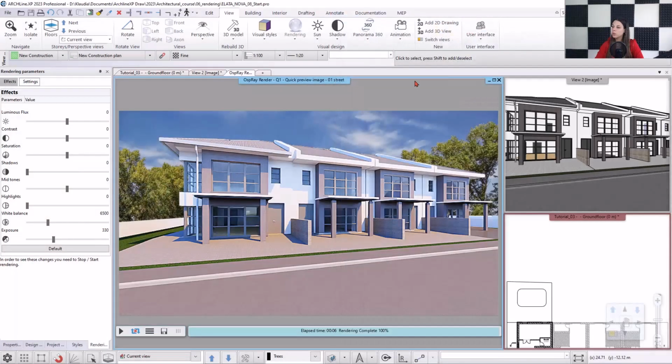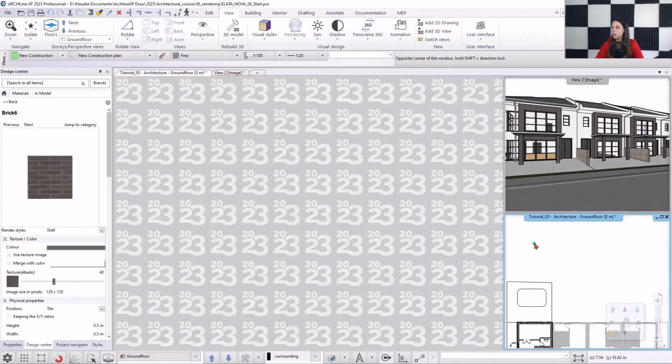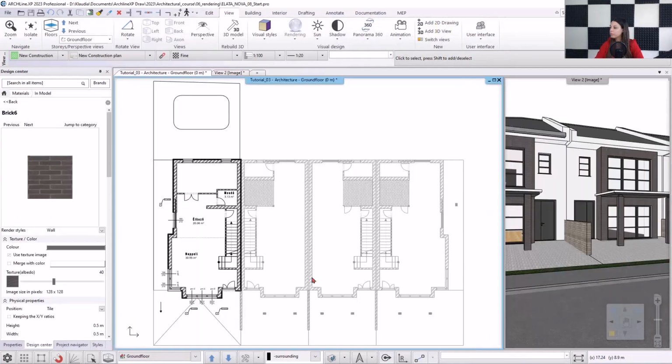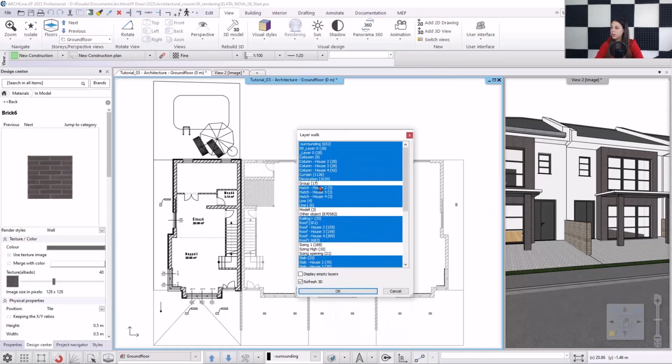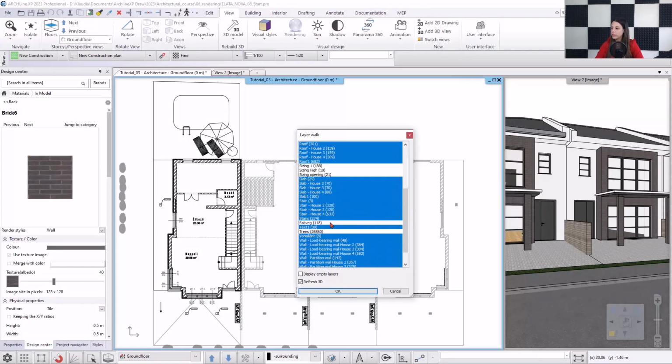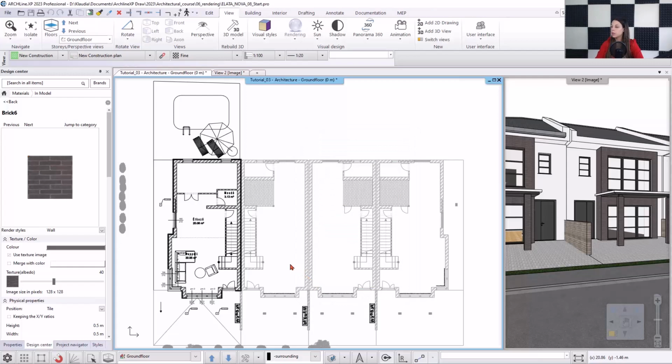To do this, I switch back the necessary layers. I go back to the floor plan, and use the layer walk to turn on the following layers: curtain, decoration, other objects and trees. I've turned these on using Control key. The Refresh 3D option is enabled, so the program automatically updates the model as I hit OK. Let's move on to the first step of the second phase.